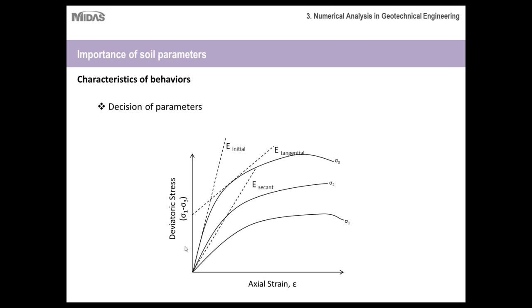So one of the main things to get from this is that soil behavior is complex and requires nonlinear behavior to be taken into account. So as you can see, based on the type of study we want to create, if we get the tangent, secant, tangential, or initial, we'll get 3 different values, all of which are very different. So it's really up to the engineer to decide what value he or she wants to use for his project.